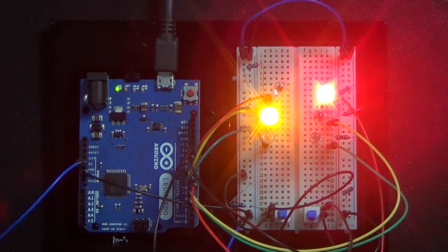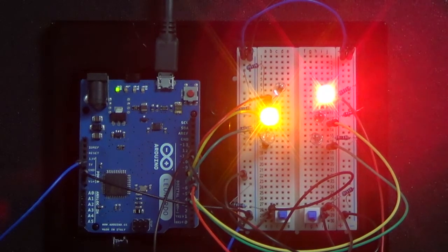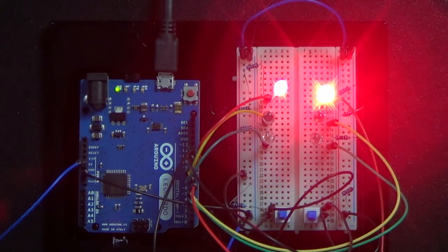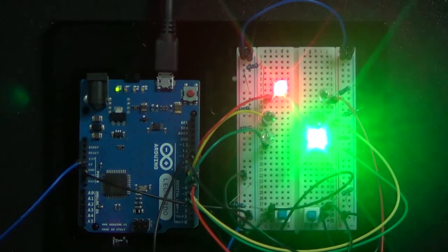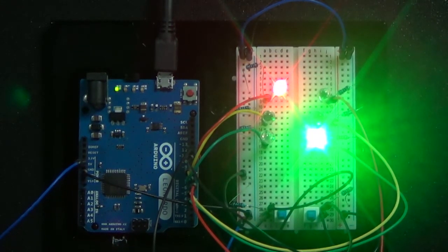And then it'll go red, and it'll wait a couple seconds till the other side goes green to let cars clear out of the intersection. Because you never want cars to, everybody runs the red light once in a while, so you just don't want to go immediately. And then this side's going to be a little bit longer. It's actually going to wait without a car for 25 seconds. So we're going to sit here and watch this light for 25 seconds, and then it'll go to yellow, 10 seconds, and then red, a couple seconds, and the other side will take over.